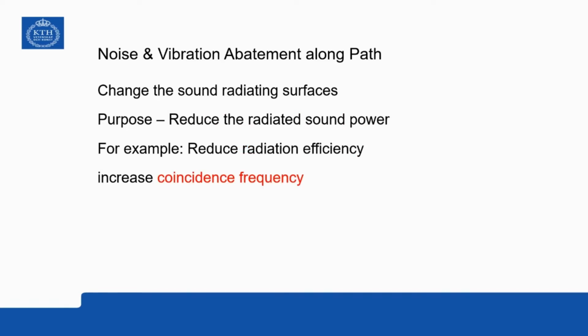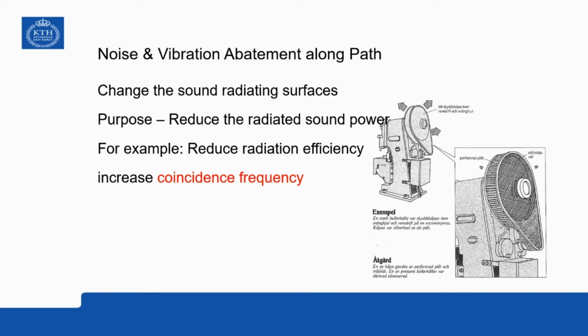One way, for instance, is to work with the coincidence frequency of the different radiating surfaces and increase the coincidence frequency. Then all vibrations with lower frequency than this coincidence frequency will radiate more inefficiently and produce less noise.